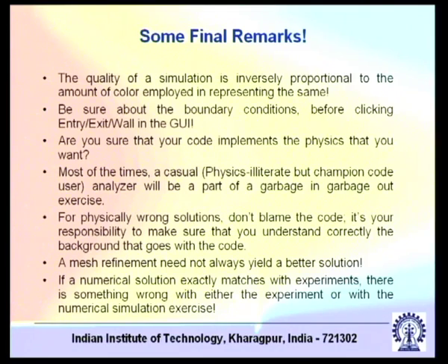Now the other thing is that when you have a solution, how do you validate it? CFD problems have benchmarks. There are some standard benchmark problems in the literature, and you can validate your solution with them. Sometimes you validate your numerical solutions with experimental results, but if a numerical solution exactly matches with experiments, there is something wrong with either the experiment or the numerical solution. The reason is you cannot perfectly match an experimental condition, which is a reality, with an idealized condition where you do not actually know the boundary conditions. You say something is isothermal, but that is not really isothermal. Then you specify certain properties, but you really do not know how those properties vary with temperature and other conditions. So your real experimental condition is not mimicked by the idealized modeling conditions.